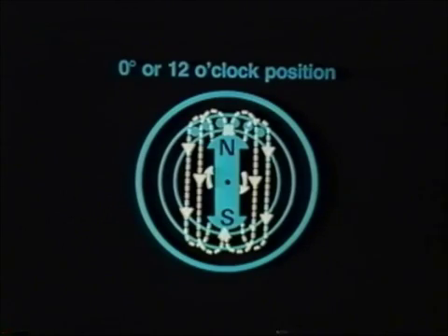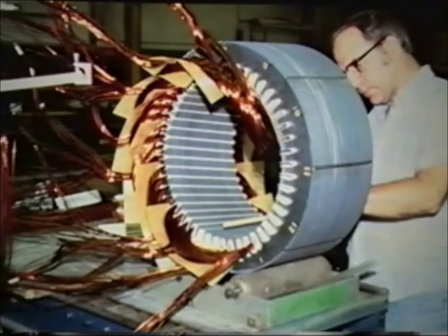Remember, a single-phase armature winding is pictured as a single large coil located at 12 o'clock. Regardless of the number of coils interconnected by the winder into a coil group, the entire group takes on the characteristics of one large coil positioned in one place in the core. Thus, one coil, single phase. Now, three-phase armatures have one coil group per phase and are termed single circuit armatures.